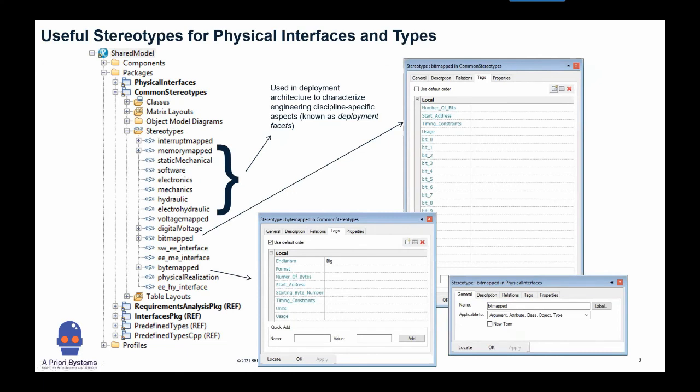It of course has the stereotype requirement, but I also add the stereotype software if it's a software requirement, or electronics requirement, or mechanical requirement, or hydraulic requirement. I do that so I can build different tables and manipulate them in different ways. I can track down the collection of software requirements. Just tagging it with the stereotypes allows me to identify those things easily when I need to.